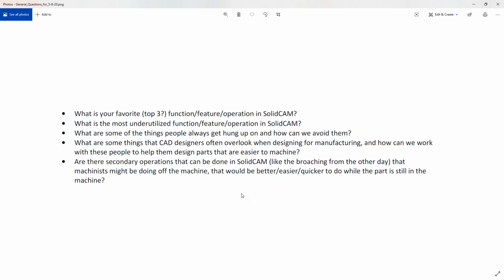So I find that a lot of people get hung up on trying to do the entire part with one toolpath, where it's easy to do a save and copy, change your technology in HSM, or with HSS, save it for detailed areas. You don't have to do the entire part. You can do different strategies for different collections of surfaces. At least that's what I have found. What do you think, Kevin? What do you think about people getting hung up on stuff?